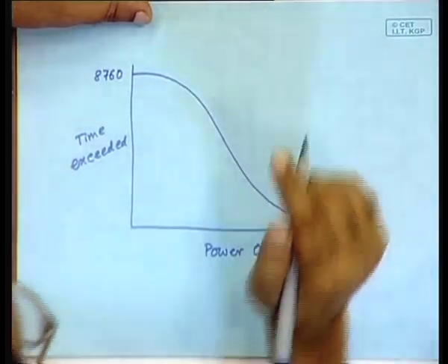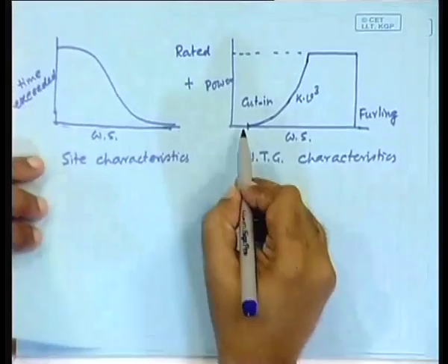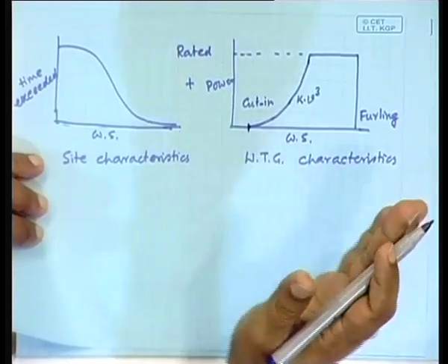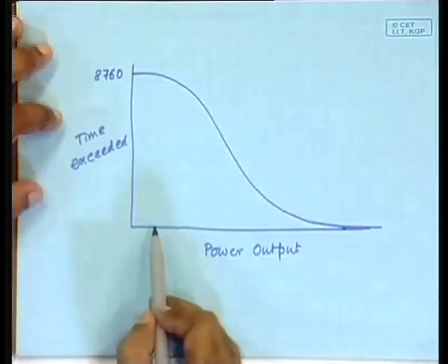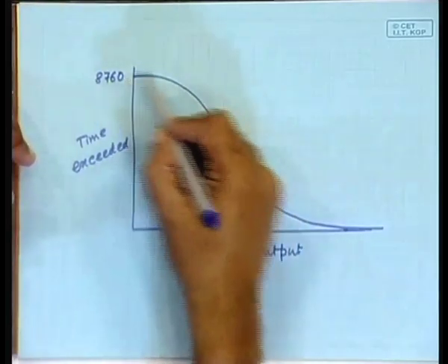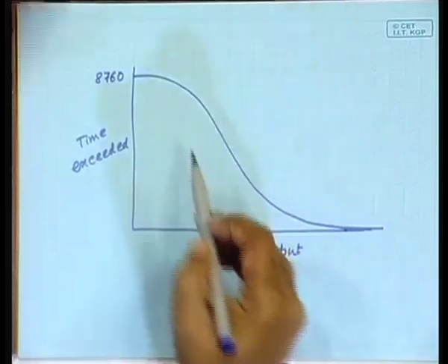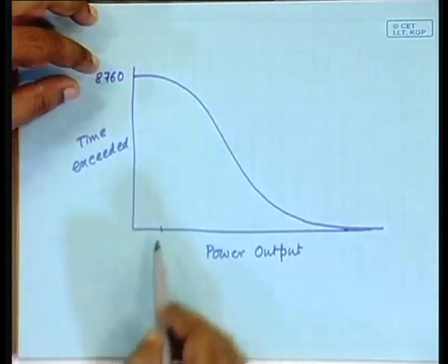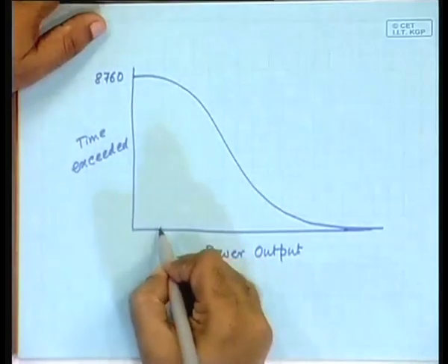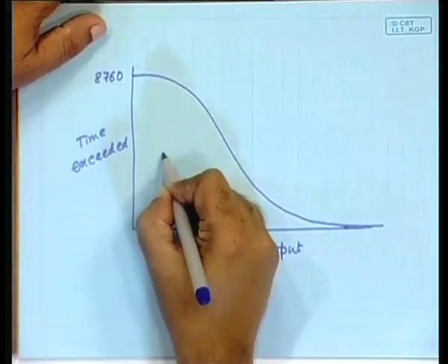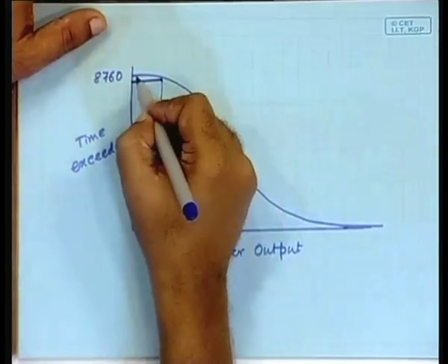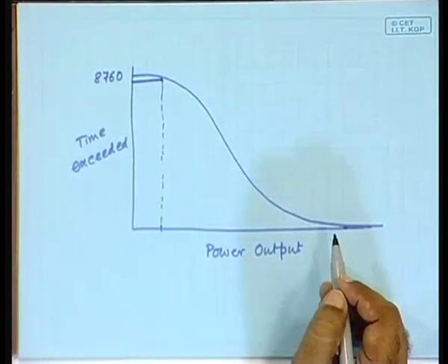Now, out of this whole time, you would see that the power generation is 0, really 0, below this wind speed, right. So, some part will be chopped off, you will not get the power output, and that is corresponding to a low value of power output. So, this is essentially the characteristic where you have cubed the velocity, but a small velocity which when cubed will give you this particular point. Below that you are generating nothing, so just go up, and here you are not generating anything. So, this part gets chopped off, you are not generating in this part.